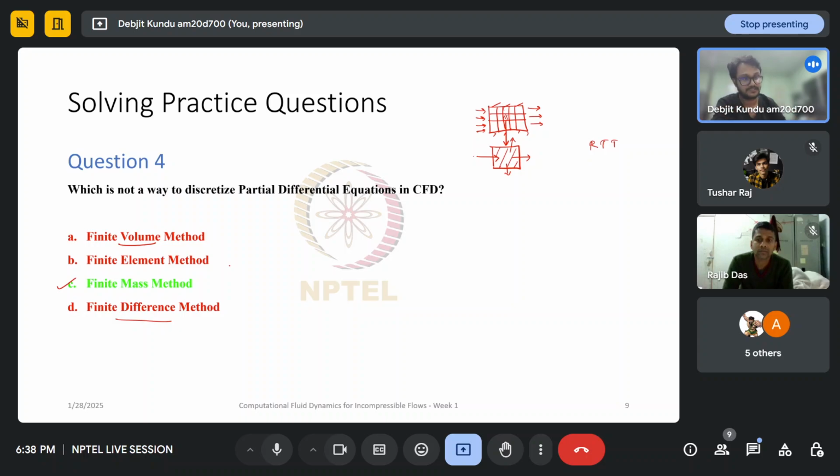It's open on all four sides. So fluid could be coming in, going out, but the whole balance will be the same. So summation mass in, because it has four faces, right, should be equal to summation mass out, because mass cannot be created or destroyed. Then similarly for momentum also, I can say that the sum of momentum in minus sum of momentum out has to be equal to the sum of forces acting on this block.